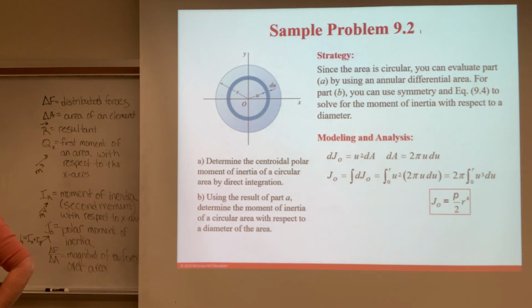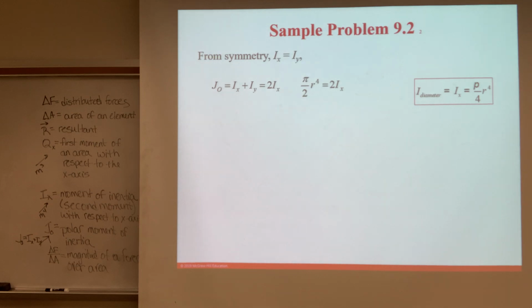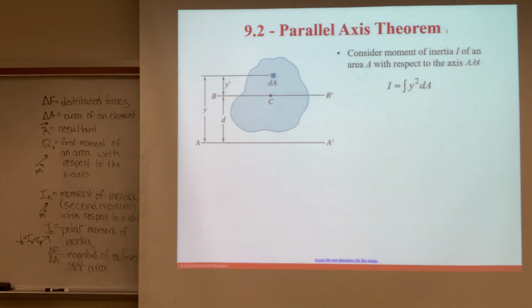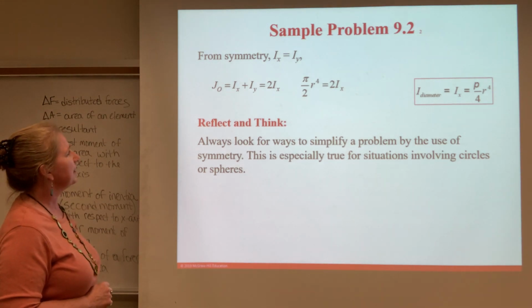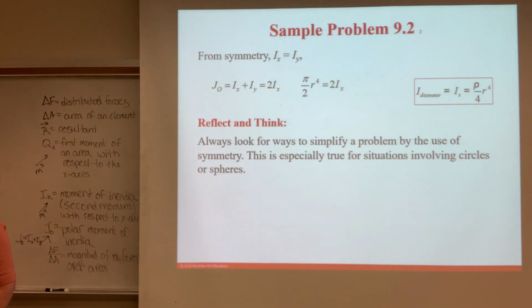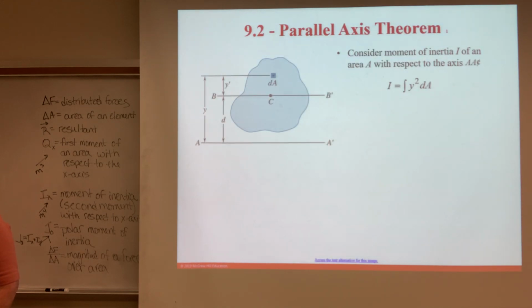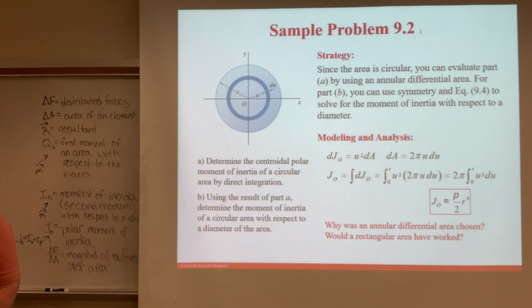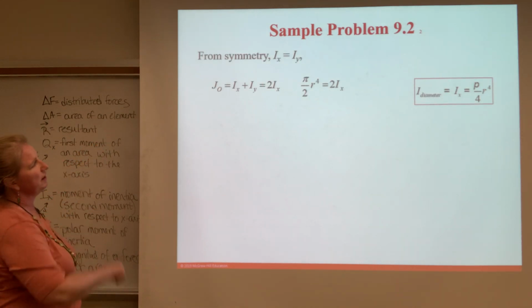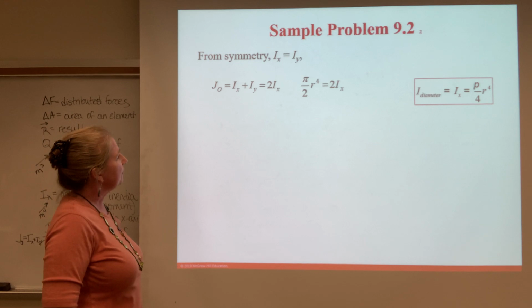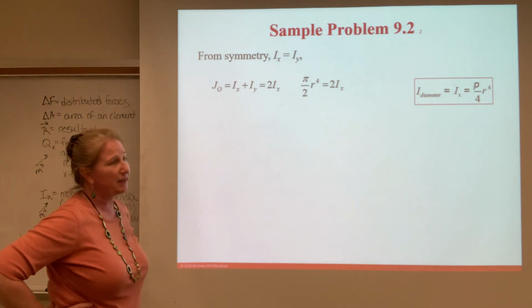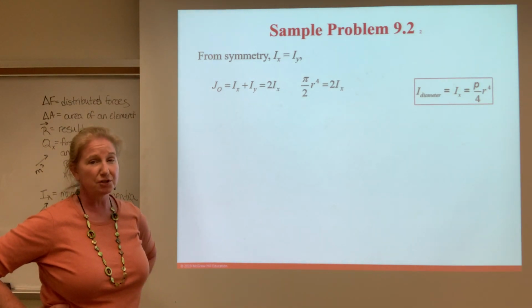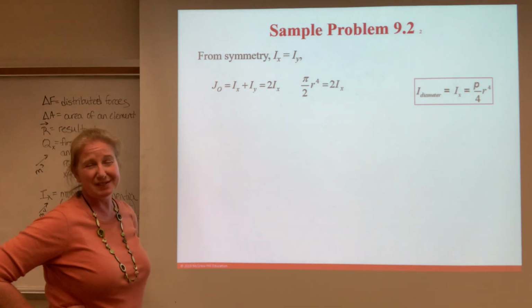Again, that's in the chart in the back of your book. Or it's in the chapter, but it's also in the back of your book. And it's posted on Canvas. All right, so for the sake of the circle, x and y will be the same, right? They're going to be symmetrical. So that's what that first statement is saying. So I could do moment of inertia with respect to x, moment of inertia with respect to y for a circle, but really polar makes more sense, truthfully.